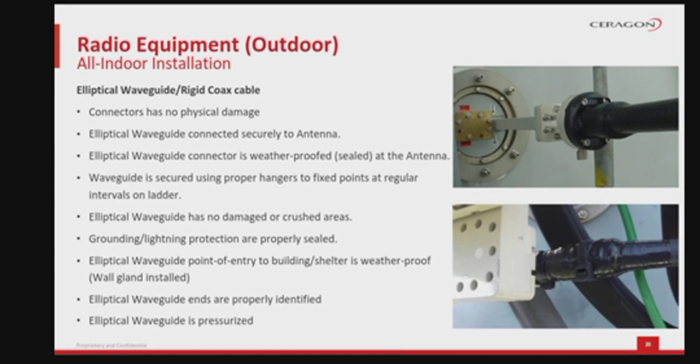For all indoor installations, verify that waveguide connectors have no physical damage, that the elliptical waveguide is connected securely to the antenna, that the waveguide connector is sealed at the antenna, and that the waveguide is secured using proper hangers to fixed points, at regular intervals on the ladder.